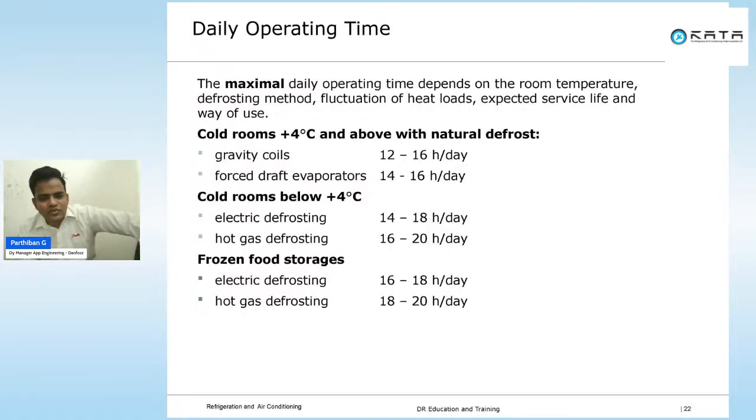Then next is frozen food storage. For frozen food storage with electrical defrosting, we consider 16 to 18 hours. For hot gas defrosting, we consider 18 to 20 hours. So this is the pull down time we generally consider.